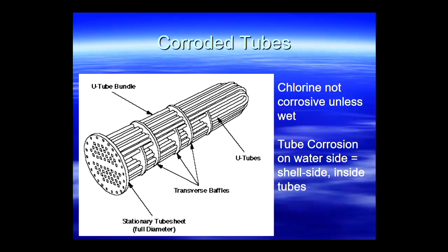I couldn't get a straight answer. I said, well, what's wrong with the cooling water? Oh, nothing. There's nothing wrong with the cooling water. I said, but if it's corroding the tubes, there must be something wrong with the cooling water. Is there something wrong with your dosing system, that you have lost control of the pH or something? Because this is right down by the seaside.